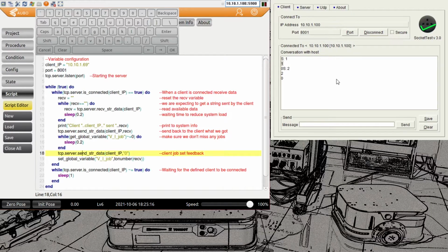So this now basically with the client, if you write your own software there, you at least know that your command is well received. Yeah, as a confirmation, a very basic confirmation. Yeah, there's a million other ways and more stable ways to do it, but it's a very basic confirmation: yes, okay, my command was actually received and I got it back. Okay, then I'm sending a 0. So the 0 essentially is only written when the global variable in the program is reset to 0. That means that the robot is executing something and is ready for taking this command.